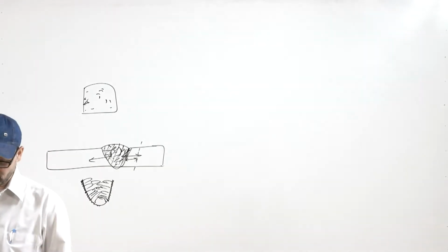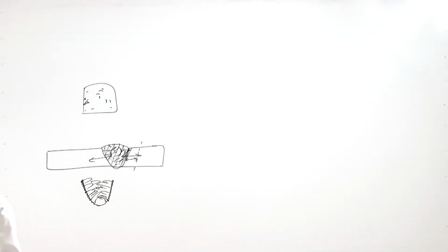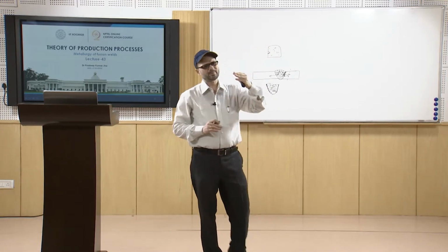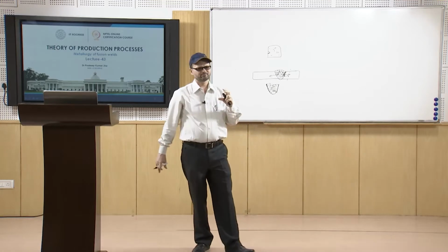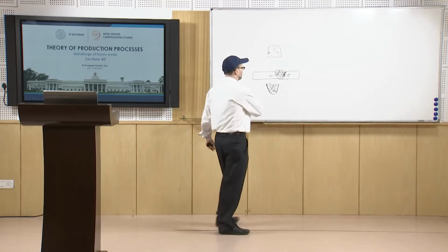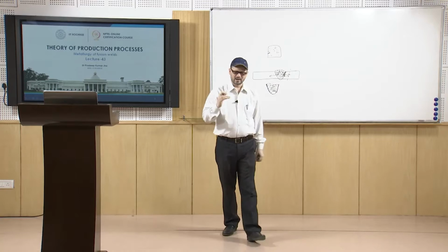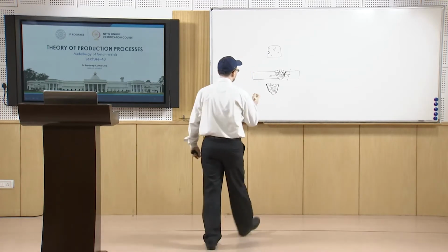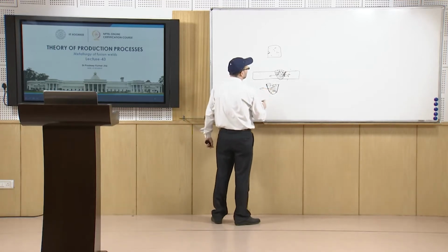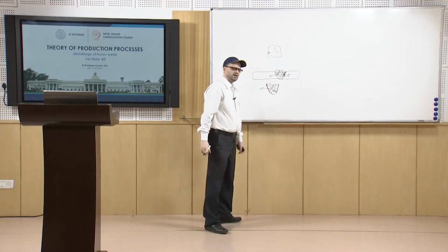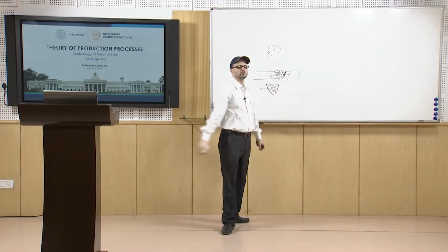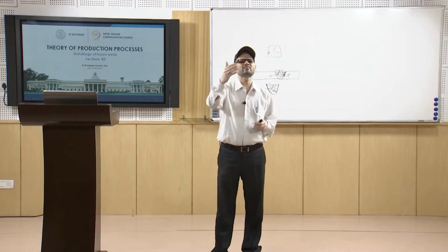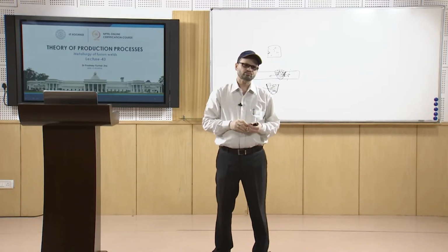Now, wherever you have the solid-liquid interface, perpendicular to that will be the direction where you have maximum heat transfer. As we know, if the heat transfer is in this direction, then your growth is in the opposite direction. That is why grains grow in that direction. Then grains also have a favorable direction to grow.